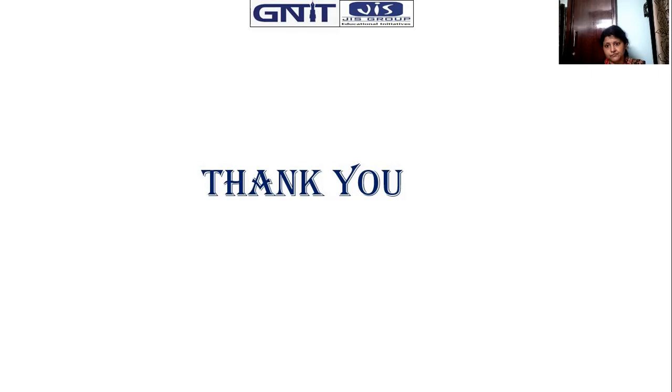Okay, after mapping. So thank you for today. We have ended with lots of information: what the basics of the Nyquist criteria are, and what the principle of argument is. It's very vital to go through the Nyquist criteria, as well as how to select the contour for a specific problem, how the mapping will be done, and then from where you collect the data of encirclement about the -1 j 0 point, if there is any encirclement or not.